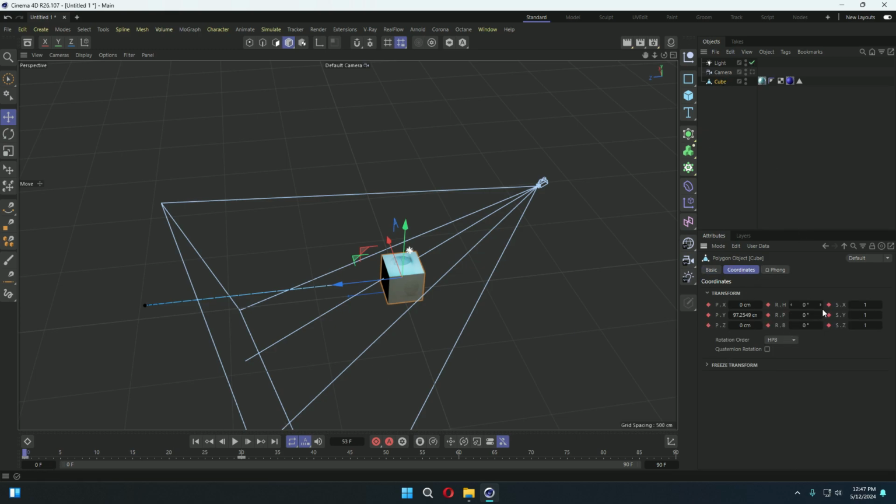And if we want to rotate it, we can animate it here as well. On 30, I want to rotate it something like minus 180, to 90 degrees. Here you can see these dots turn yellow. It means the keyframe is not yet confirmed. You have to click on that yellow keyframe to make it red. Now our keyframe is set. You can see now it is rotating and moving.